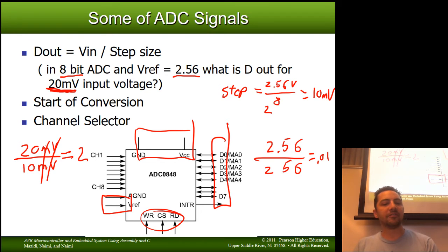We'll just divide the input signal by the step size, and that's your reading. If it happens to come out exactly right, well, good for you. But chances are we're measuring a time-varying signal, so there'll be a little bit of noise one way or another, and we won't have to worry about being off by one least significant digit. Okay, so there we go.